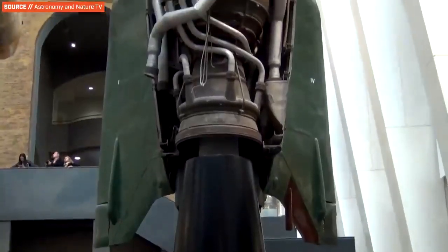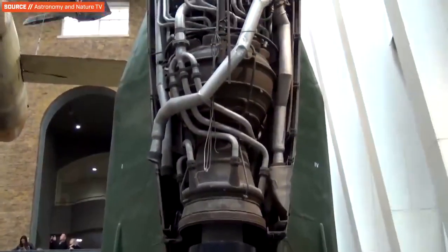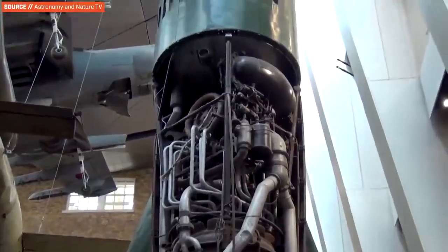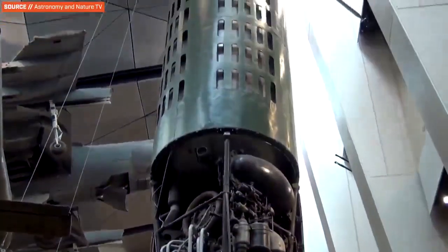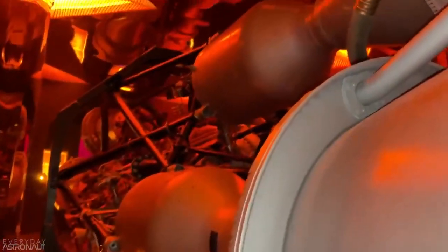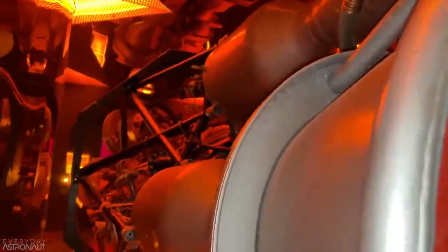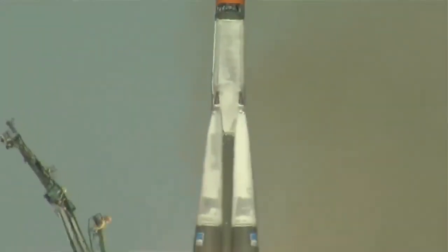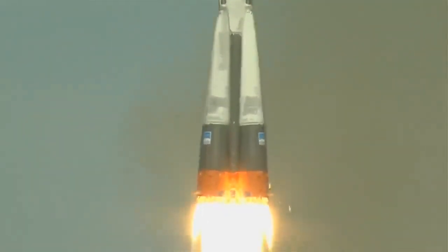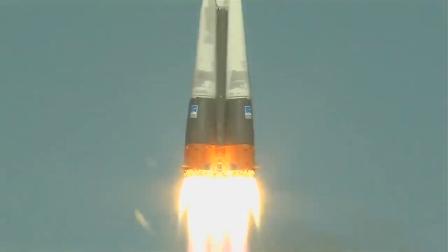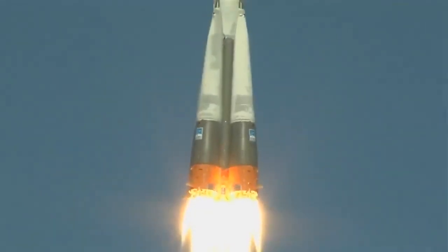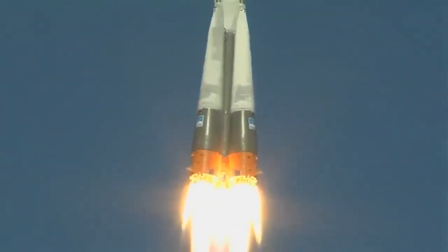I like this solution because it's using a simple pressure-fed monoprop rocket engine to spin a larger, more powerful pump to increase the overall output of the engine. It's a pretty clever idea, and it's still in use today on the Soyuz rocket on the RD-107A and the RD-108A. But that's a little less efficient to have another set of tanks for your gas generator fuel, and then you're also only getting the energy from a monoprop engine, instead of just tapping into the high energy rocket fuel that's already right there inside the rocket.